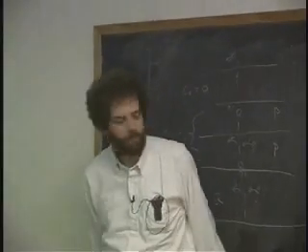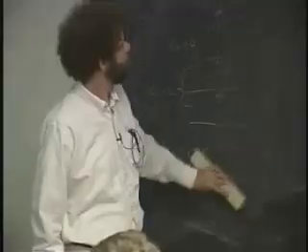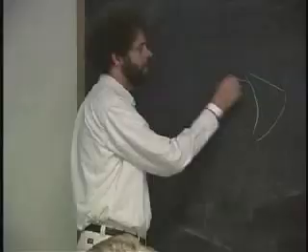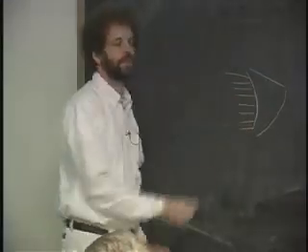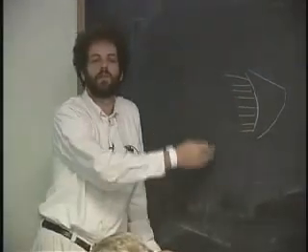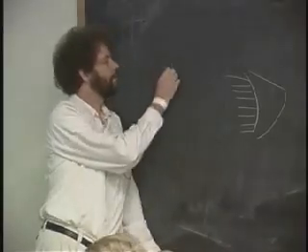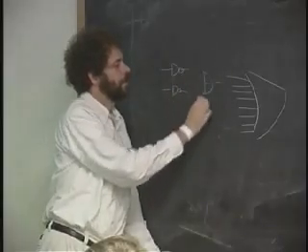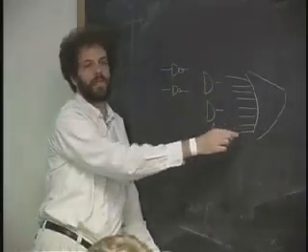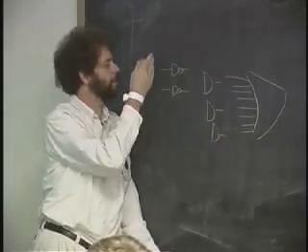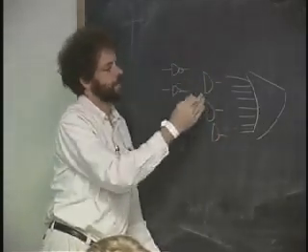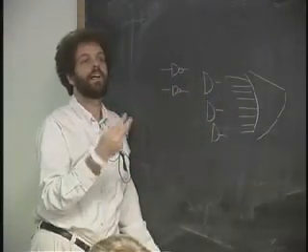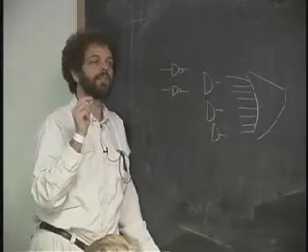Now, if you have gates like the huge OR gate that I talked about in the sum of products form, where you have a gate of a gazillion inputs, then sure, you can do it in a very small number of stages. You know that you can do any function in 3 stages of inversion, ANDs, and an OR. So theoretically, if this is 1/billionth of a second, and this is 1/billionth of a second, and this is 1/billionth of a second, it should only take at most 3/billionths of a second to do any function. But I'm telling you that's not true.